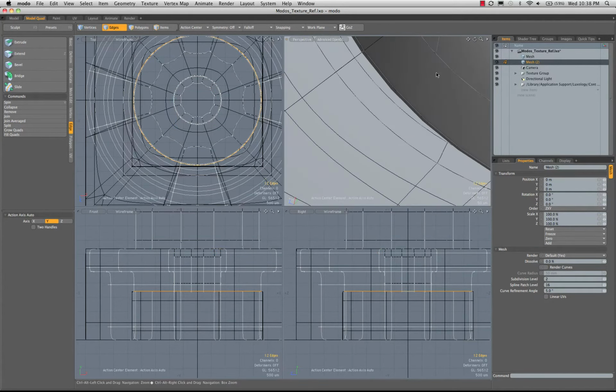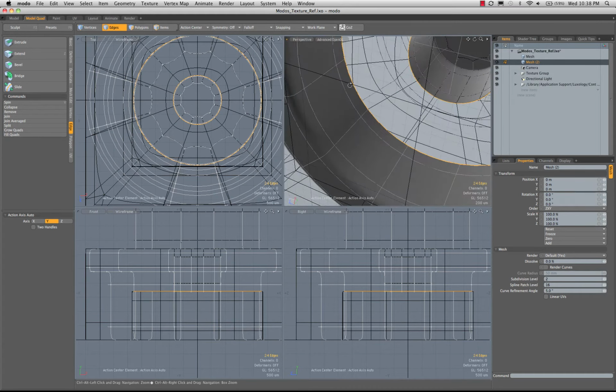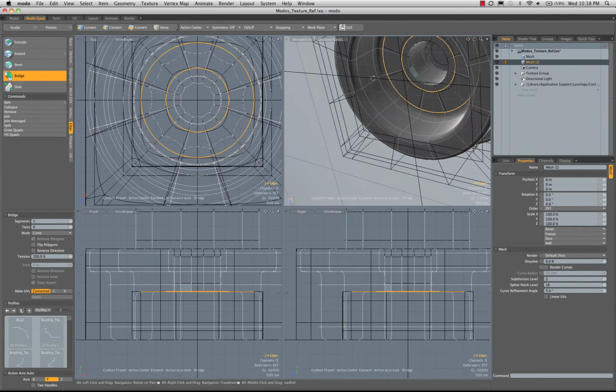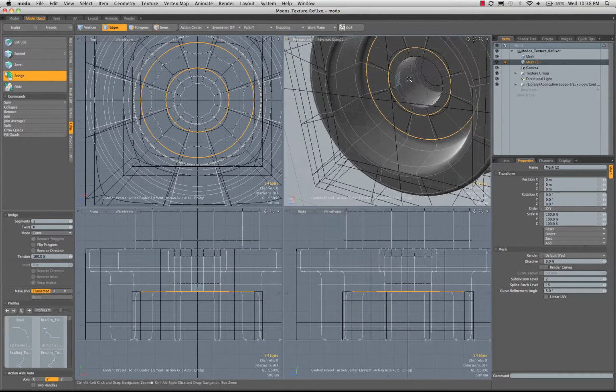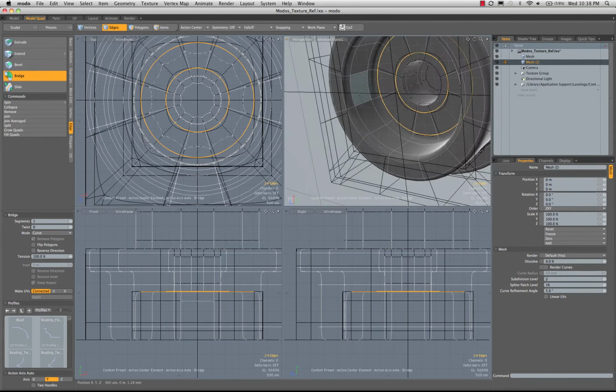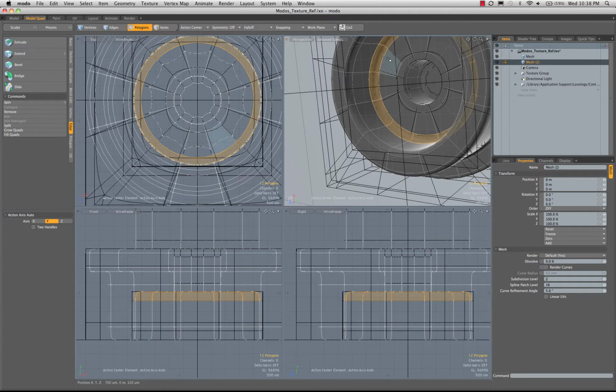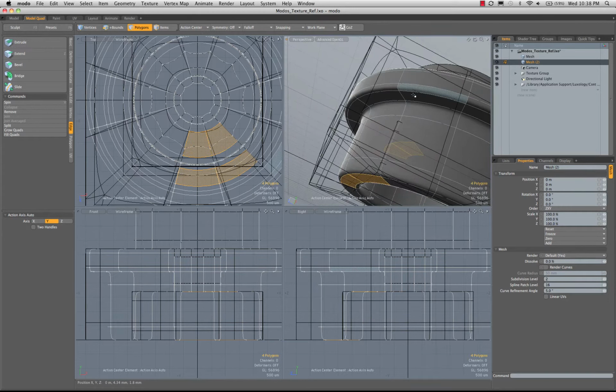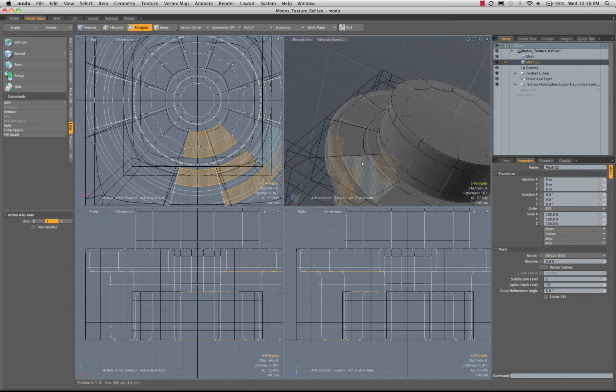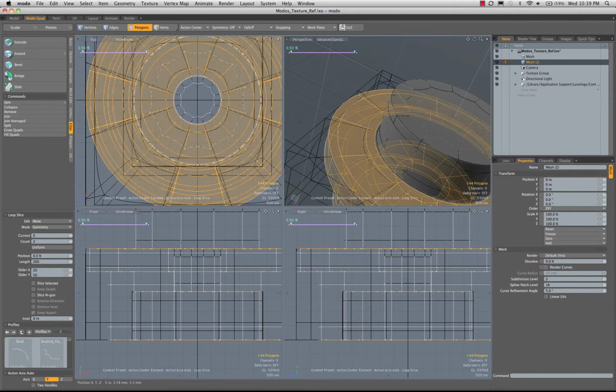So now I can drop that tool, and let's select this inner rim here. Now you can see they're actually lining up, so we can run our bridge tool and we know that we're set. Since we already had this geometry set for sure, we want to kind of defer to that as far as making any adjustments. So I'm going to go through here and do our loop slices that we'll need. So here, here, here, here. We'll actually have 2 to delete if we do this, but that'll be all right.